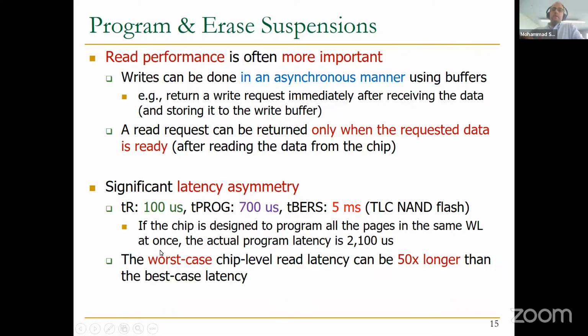Also remember that if the chip is designed to program all the pages in the same word line at once, the actual program latency is 2100 microseconds. Since this is TLC NAND flash, you should be able to store 3 pages at the same time.